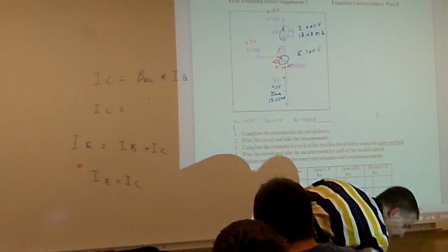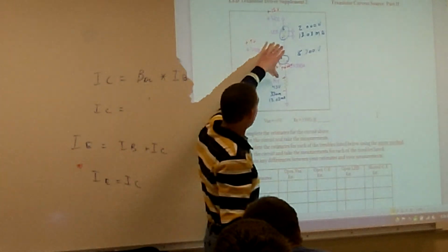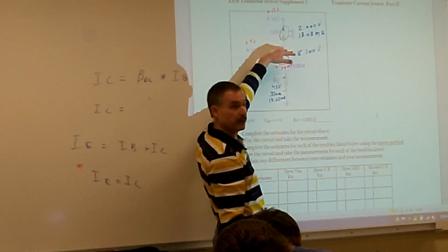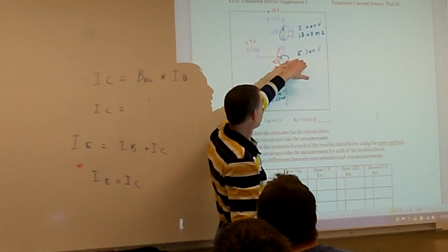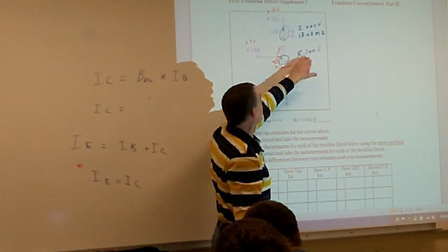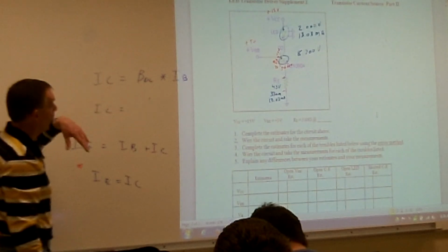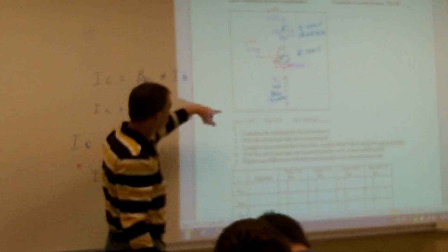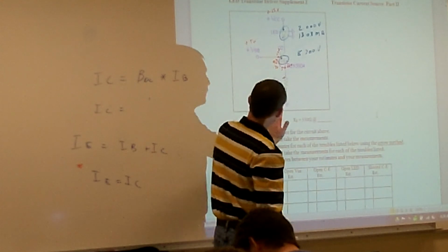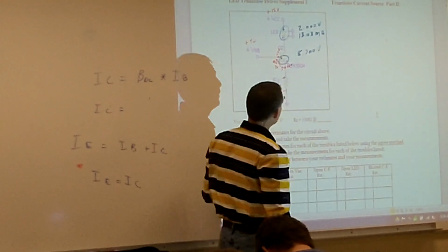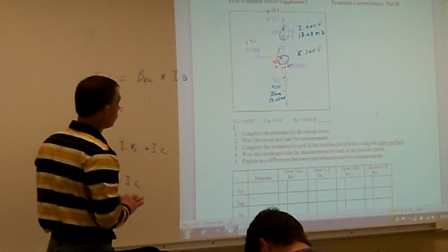Okay? Now the LED is still turned on. We're not in saturation, right? Because we're not measuring our source, and we're not measuring our 0.2 volts going across our collector emitter. But yet the LED is being turned on in this particular case. Okay? The current is being controlled by RE. We're going to make sure that we have 13.03 milliamps of current going through there.